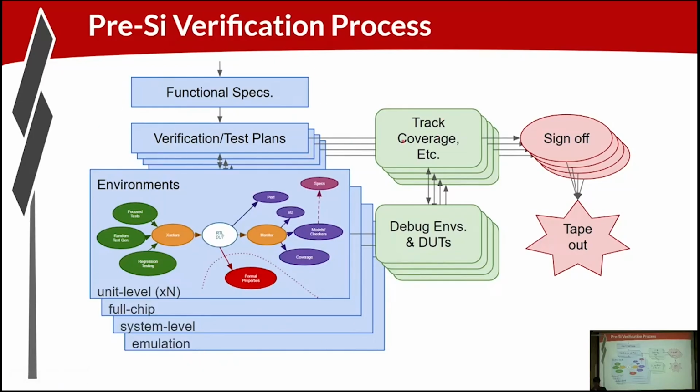So these are the models. This is the work. You're going to be using the verification plans to count through all of the items in the plan and make sure you've got tests that achieve the desired coverage goals. So the test plans are going to incorporate a specification of what all the coverage is that each category of testing is trying to hit. And then the coverage monitors are making sure that you hit those cases. And that's giving you a level of confidence that you're exercising the logic, all the corners of the logic as best you can.